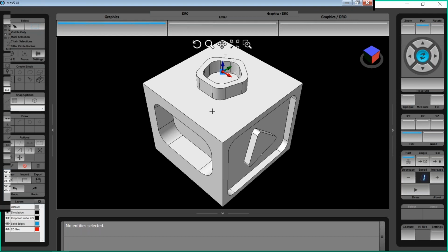So you're not limited to keeping the tool normal to the surface. You can actually tilt the tool 20 or 30 or 40 degrees and then use the radius of the end mill to surface, as opposed to using the tip of a ball end mill. But right now, I think we're still working through the ball end mill stuff. But we do plan on supporting bull nose tools eventually.